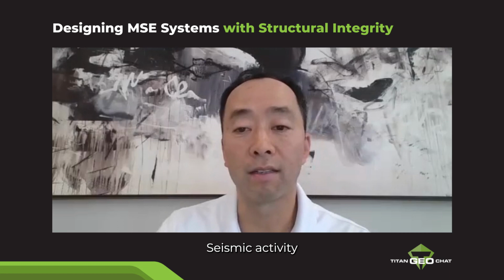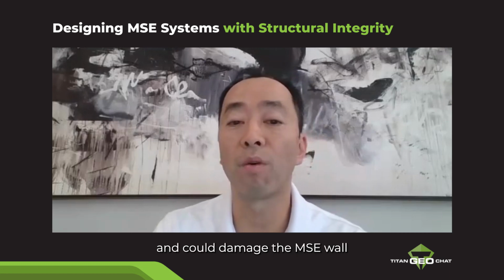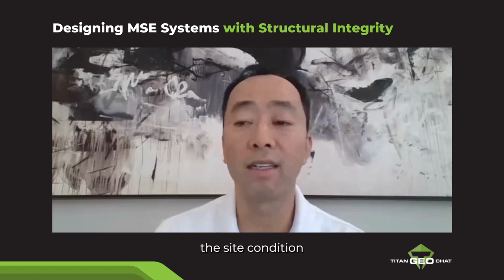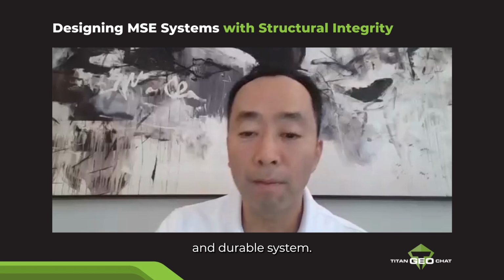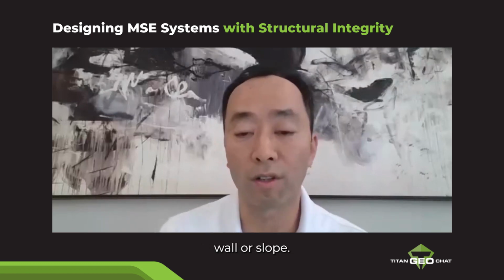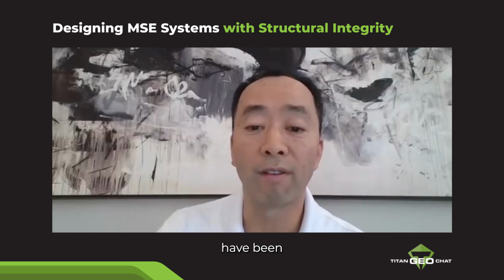Seismic activity, such as earthquakes, can cause the ground to shift and could damage the MSE wall or slope structure. Engineers must carefully evaluate the site condition and select appropriate reinforcing elements and construction techniques to ensure a stable and durable system. Proper construction is also critical for the stability of the MSE wall or slope. Most of the failures that I have seen personally have been from incorrect installations.